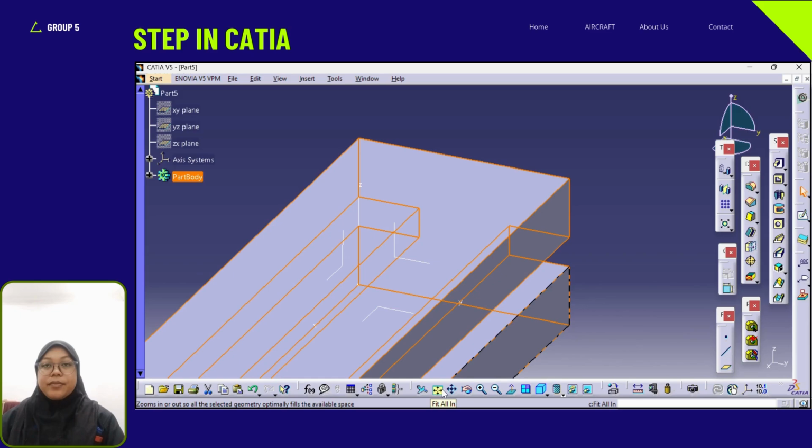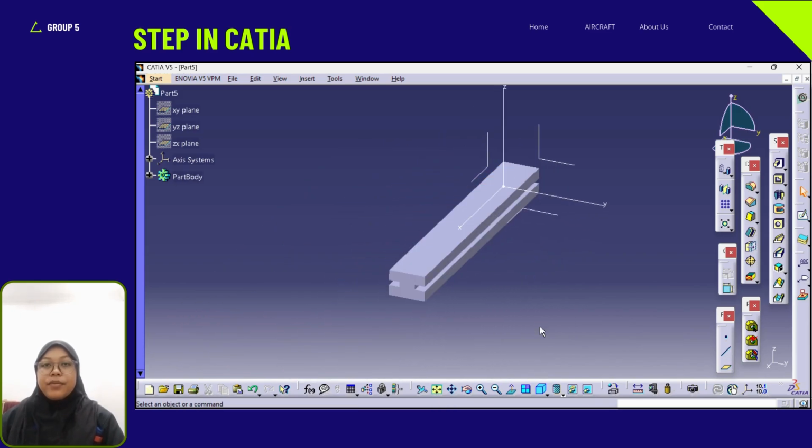First, sketch I-beam, follow the dimension given. Pad width 500 mm. Select all the edge of the beam and choose Fillet option to get fillet edge.